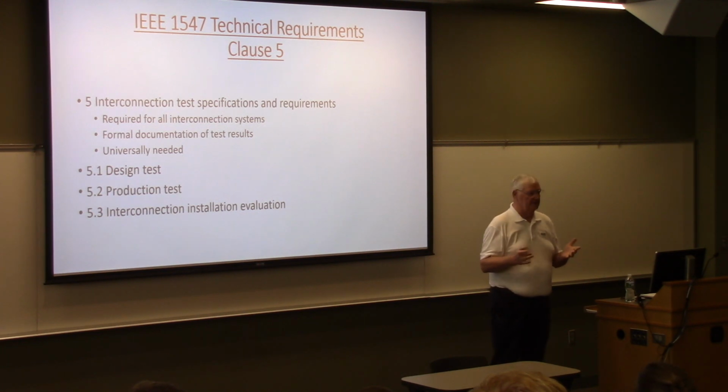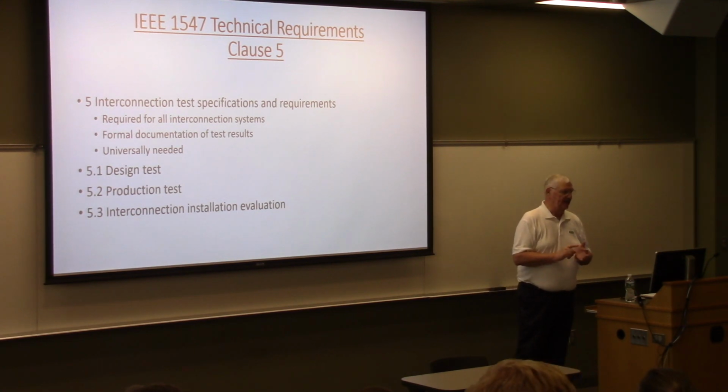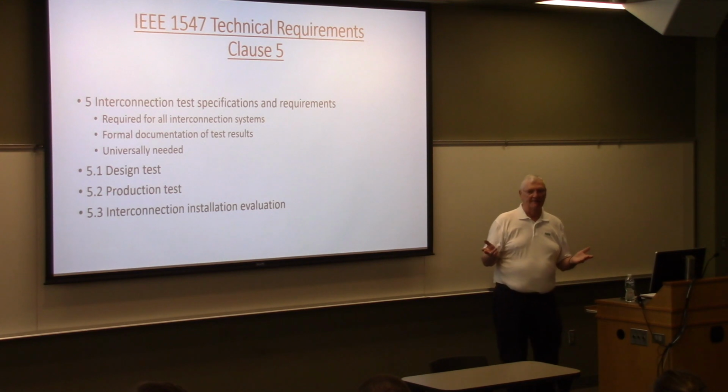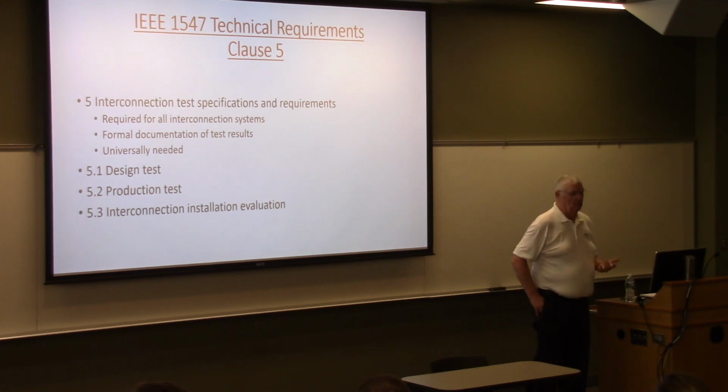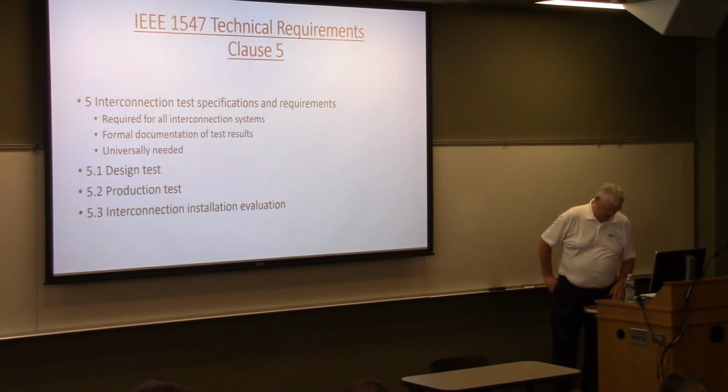If it's an adjustable device, you would evaluate it at the min, mid, and max setting of the range at those 3 temperatures. And if it had a time function in it, you would measure it at the min, mid, and max time parameter. So that's a lot of testing. But you only do it on one product, and you're generally doing that while you're developing the product anyway. And it's a standard requirement in order for it to get a listing to UL, which is required by the National Electrical Code. So it's not an encumbering requirement in the standard.